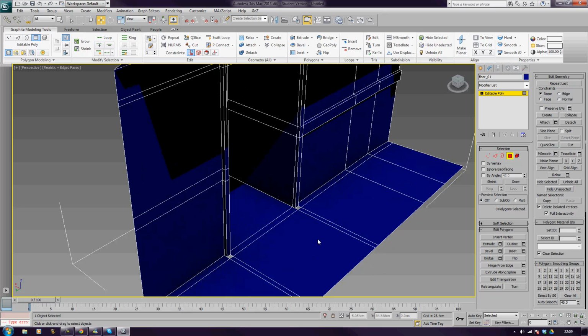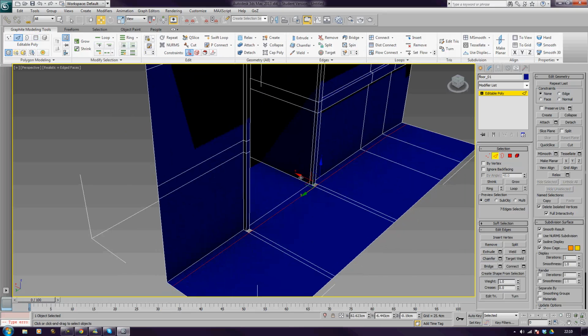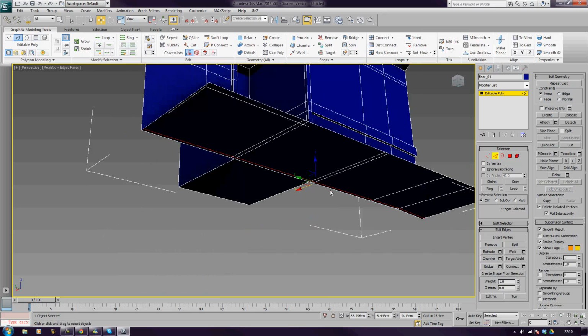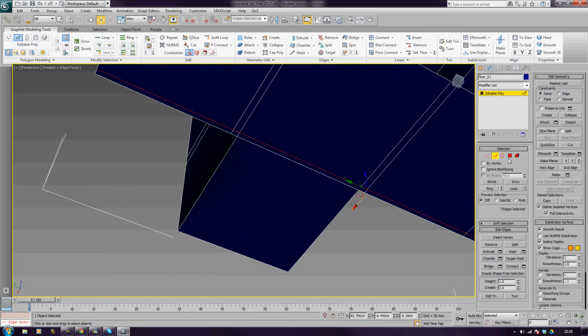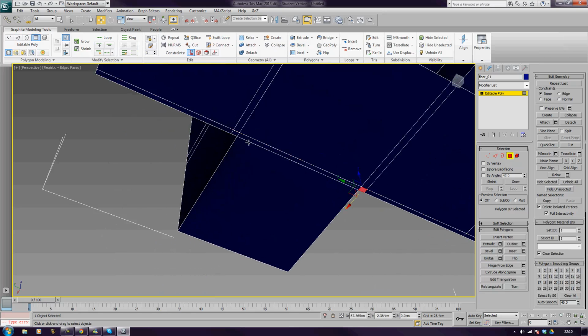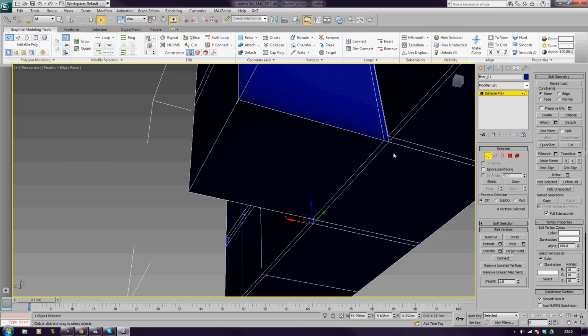And then if I go in and just get these parts so they're all flush, turn my model upside down, and I'm going to delete just here and here, like that. Okay, and now if I just select by vertex, just using the select tool, do a marquee here and here, and just click weld, and it will bring up this little box and we can see that we've lost 4 verts. That's what we want. Click tick.